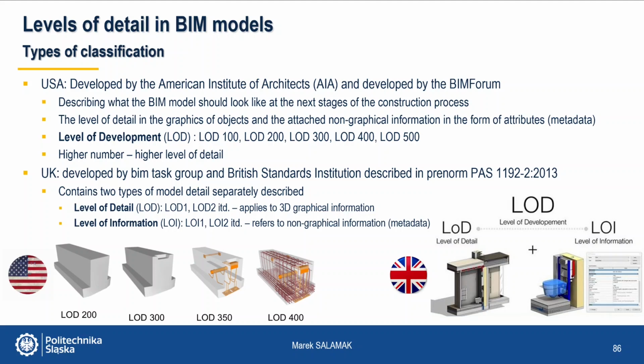The American LOD is a classification that describes what a BIM model should look like at the next stages of the construction processes. It determines the level of detail in the graphics of model objects and the non-graphical information attached to them in the form of attributes. They are called metadata.